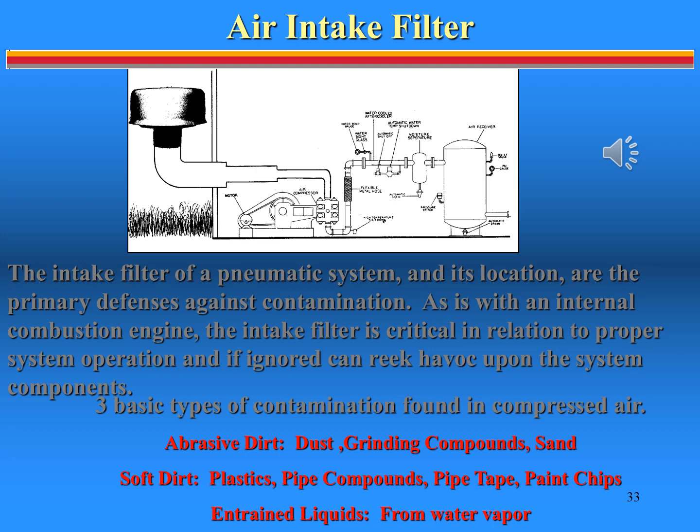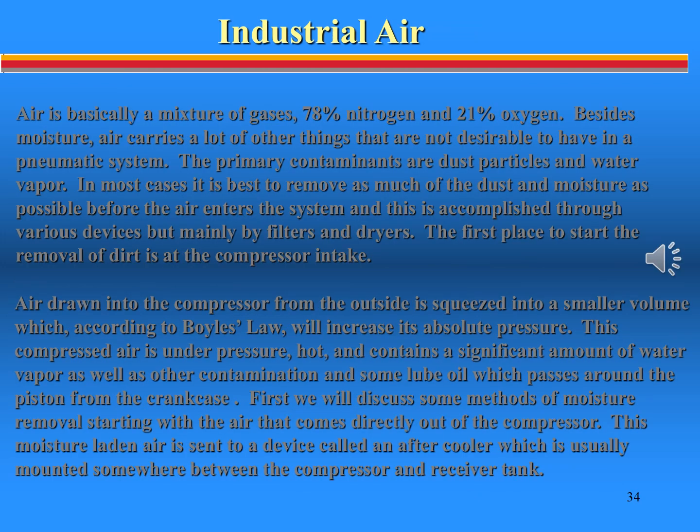In the Mid-South and to the East in North America, humidity levels in the air cause excessive buildup of moisture in the compressed air system. When the compressor takes in air, it is at a large volume, but then is compressed into a smaller volume. The humidity that existed in the larger volume is now in the smaller volume. Moisture in the compressed air system can cause many problems and must be removed.